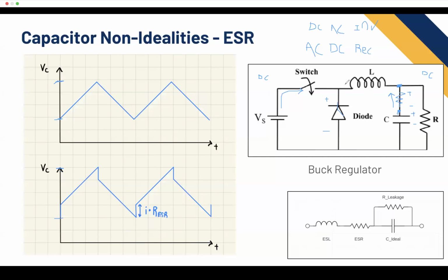Current is going to go through our inductor and charge it up, because when you have a voltage across an inductor, it'll start charging, but if there's no current through it before, it'll resist changes in current. And then that current will go through, and some of it charges our capacitor, which discharges in the next state, and some of it powers our load.